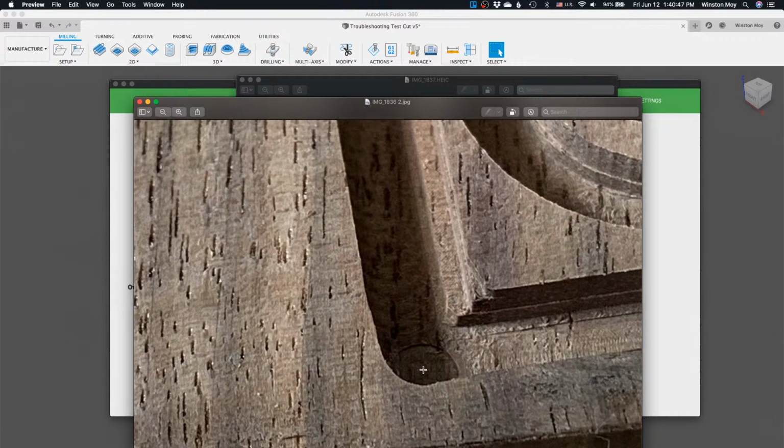That's again because the belts are not tight, so there's a little backlash. As the spindle starts pushing upwards through this material, the cutting forces nudge the spindle over a little more, stretching the belt and causing the cut not to be straight. So if you tighten up your belts, you can straighten out the path that the spindle will take.